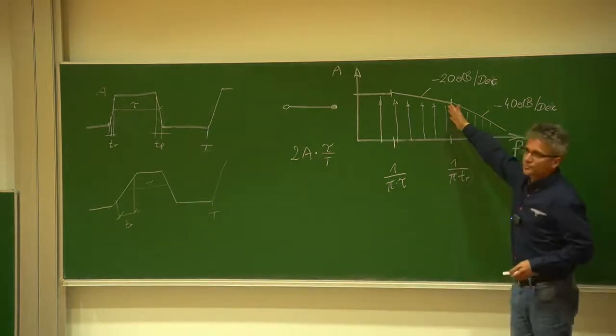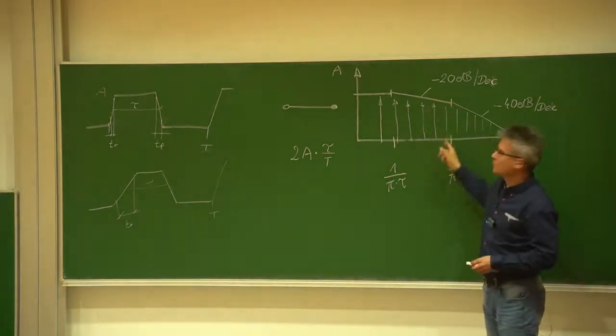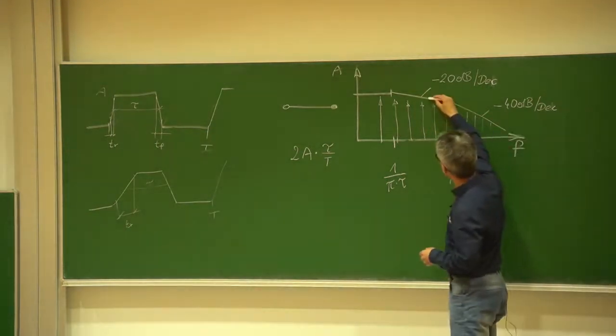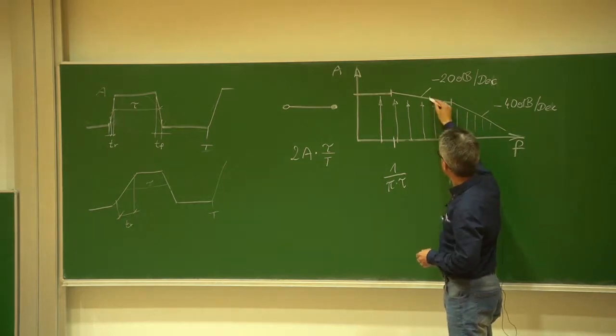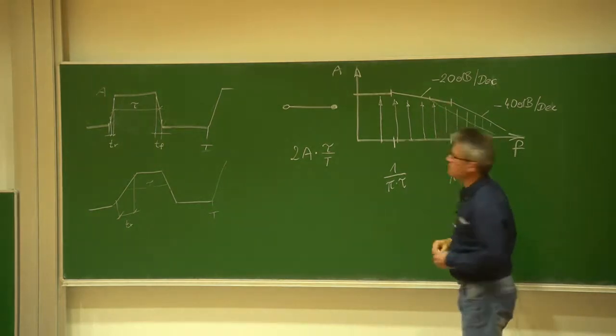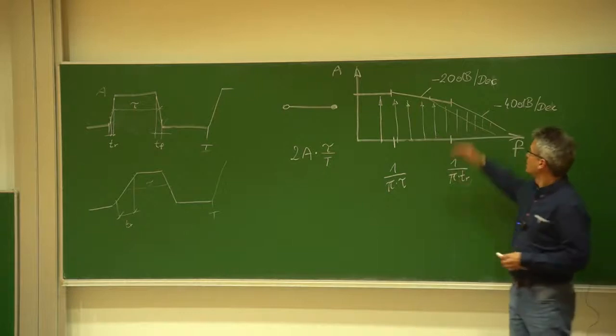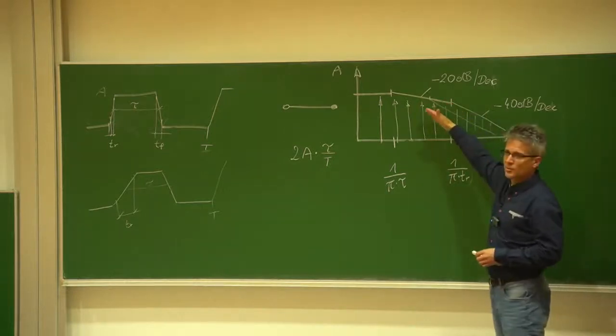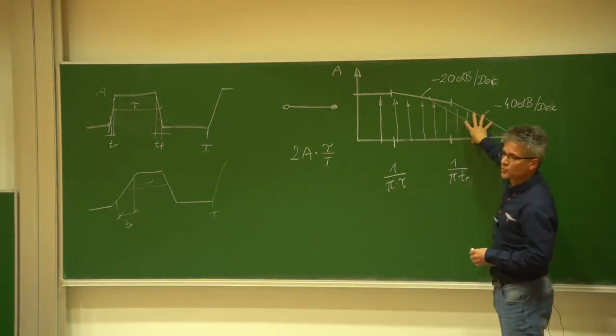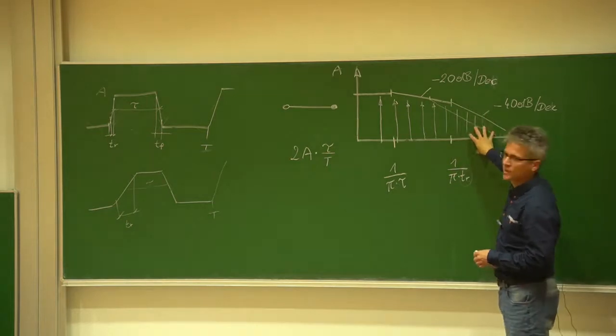And this will then decrease this frequency point. So it moves down to, for example, this frequency position, and then this minus 40 dB per decade declining function starts a little bit earlier, which is reducing the electromagnetic emission here in this higher frequency range.